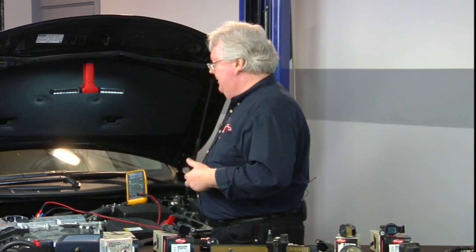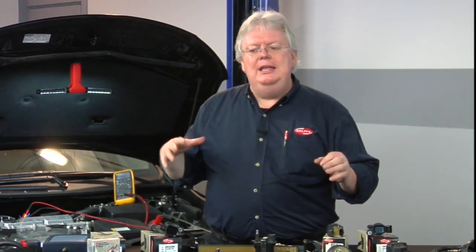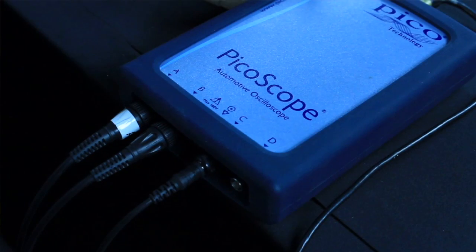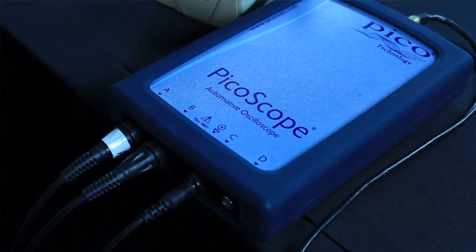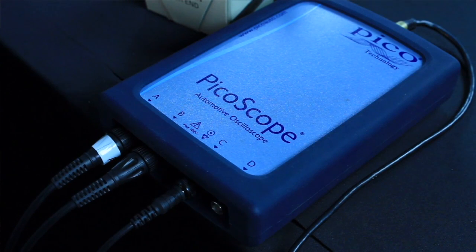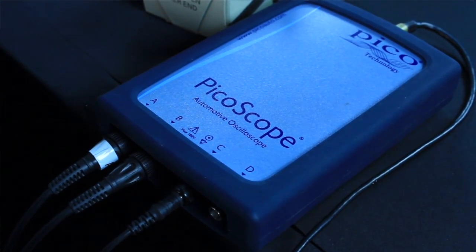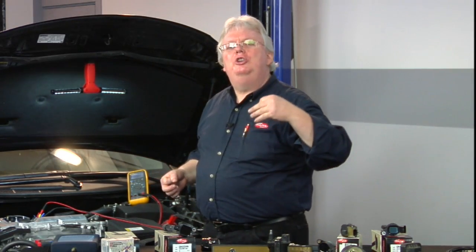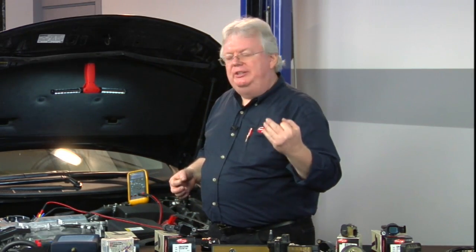Now, if you have a lab scope built into your scan tool, standalone lab scope, like a nice 4-channel Pico PC-based scope, or maybe you just got one of those little single-channel scopes that you can pick up for a couple $100, get scoping. You're going to be using it for a lot more than things like this, but this is bread and butter, so you don't use this level of diagnostics every single day, but you need to be proficient at it enough to where you can use it once a week when you get the tough job.